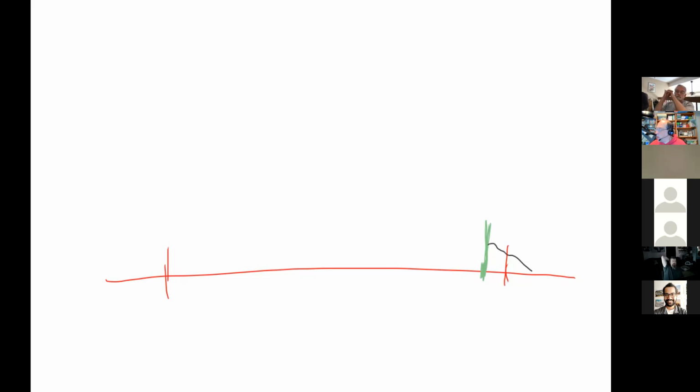So what would be our remedy for this, assuming that this was the mode we wanted to operate on? Move a little bit to the left. That's right. We'd move our signal to the left and then our signal would fall right there. And then we'd be okay. And that is why you never set your frequency to exactly on the limit, because depending on what you're doing, if your radio is off by a little bit, or your modulation sidebands hang out over here, or it over time changes by 1 kilohertz, all of a sudden you're not in band anymore. So that's why we don't go all the way to the edge.